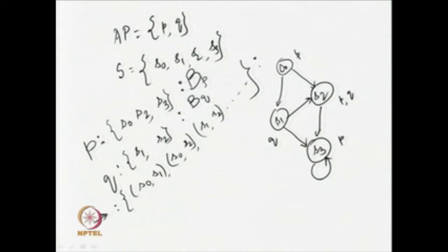And these are the state transitions that we have in our system, and already we have seen how to represent this transition behavior of the system with the help of ROBDDs. So, I can say that this B arrow is the ROBDD representation of this transition relation. And you just think that if I am talking about ordered BDDs, all these BDDs have a compatible variable order.